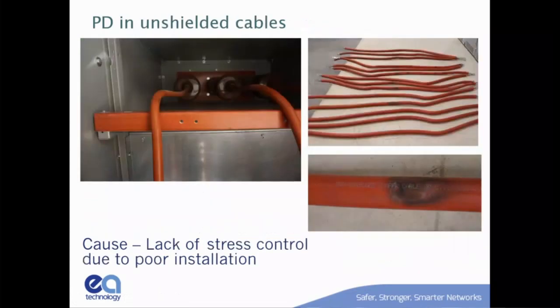This is from a full-time monitor system. And what they found within a few months of operation, that these cables, which are 35 kV, 34 kV cables up to PTs, are resting on these insulators. And this is what happens at that point where they're resting on the insulator. That's the burning that's starting from partial discharge. Because you have this cable, there's no shield, and you have this sharp edge of the insulator, even though they're all insulators, it's still a geometric concentration of field, and that caused that discharge to occur.